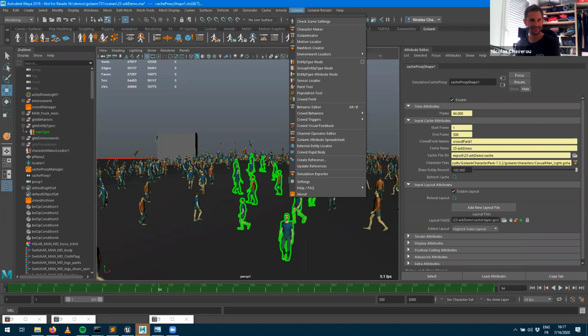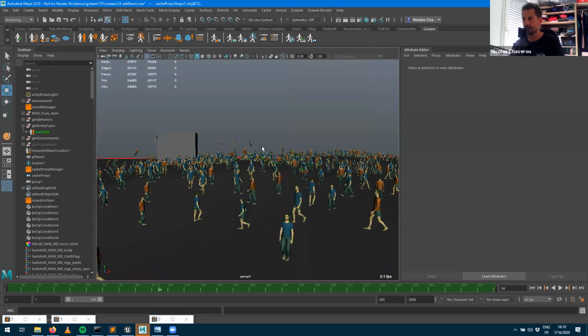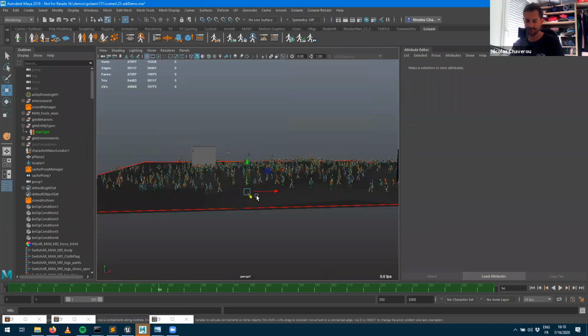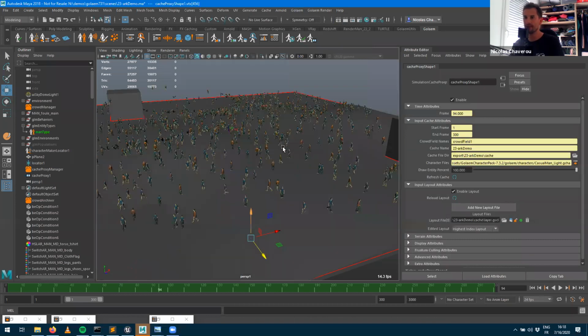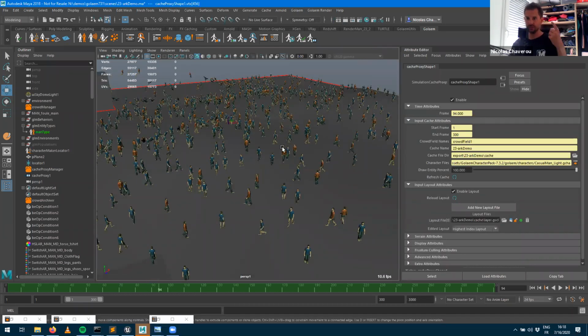Okay, cool. Is it based on .ass, Arnold's file format system? We could, but we're not really taking advantage of it. ASS is the internal file format for the Arnold rendering engine. If you were to generate an ASS file for that, it would be a really huge one, gigabytes of data, even if compressed. So we have an Arnold plugin which creates the geometry and writes the ASS at render time. So you never have to have those huge files that you can't really handle. We just generate that on the fly in memory. But if you want, you can still do it.